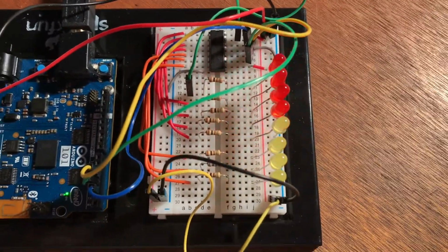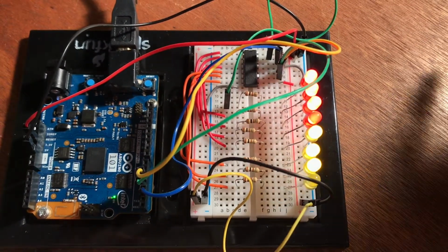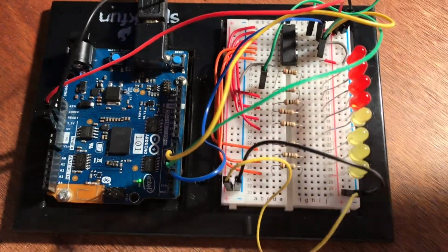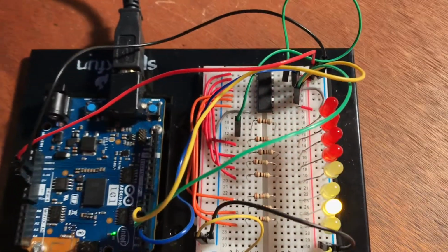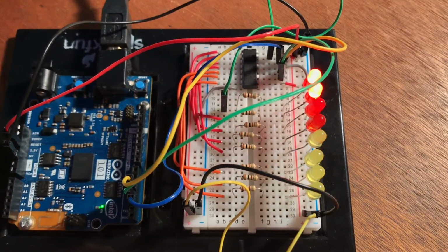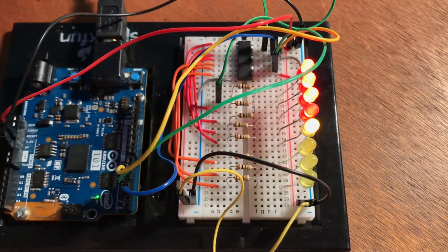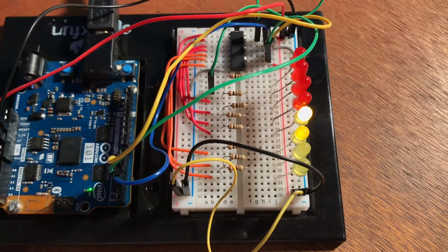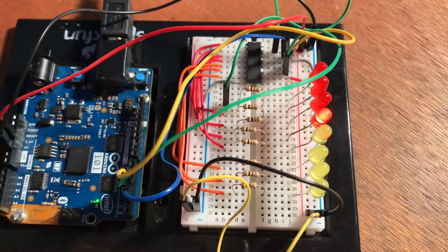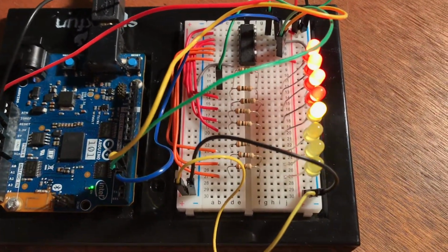So in the shift register, you can control up to 8 outputs, and they're useful because you can control 8 outputs while only using 3 pins on the Arduino board, so that's really helpful when saving space. How this works is that you load all the bits in first, and once they're loaded in, then the latch pin can be pulled, and each LED will either turn on or stay off, depending on the information that was loaded into the shift register.